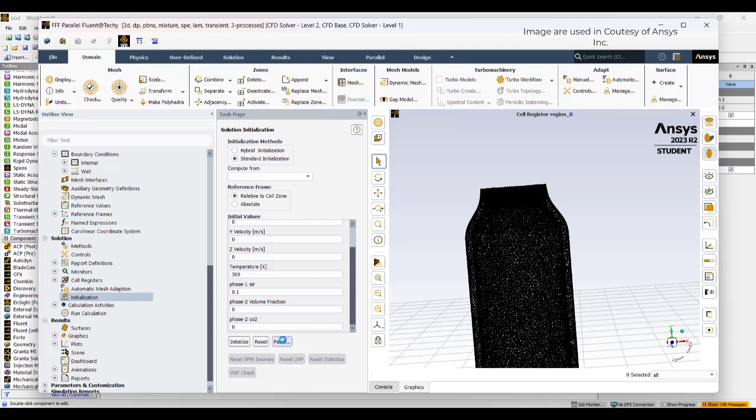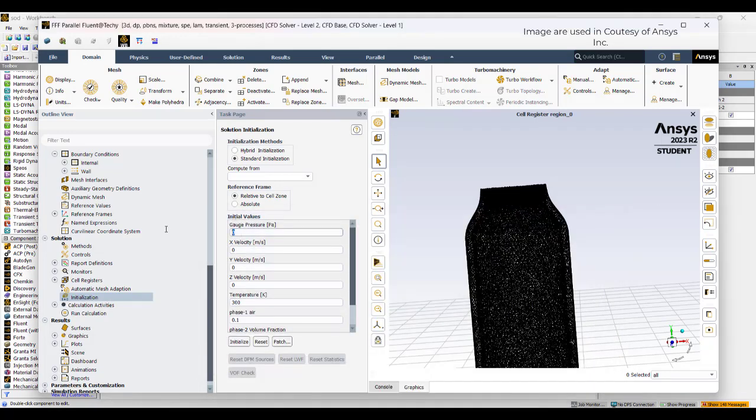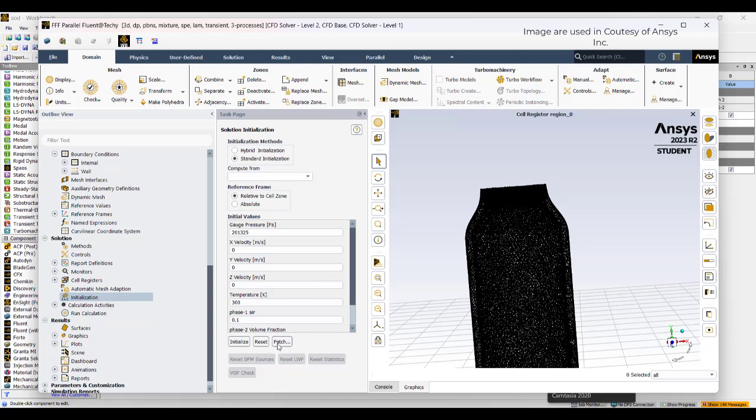So what happens to the carbon dioxide content in the water? It should increase according to Henry's law, right? So what is the percentage with respect to the time, how it is increasing? We can just check in the post processing. So patch the pressure value, maybe I'll take 201,325 for this. Sorry, previously we need to patch everything with the value 201,325. Initialize. Now everything is at the same pressure.